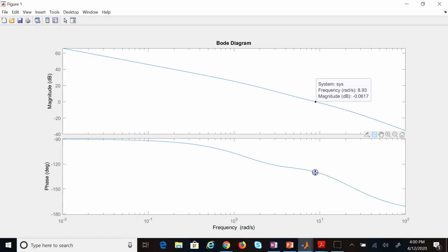It should be about 50 degrees or more. And you see it is. The phase of the system is negative 130, and when you add 180 to it, you get 50 degrees. So although I added 5 degrees extra, my new phase margin is exactly 50 degrees, as I wanted. It's not 55 because the gain crossover frequency shifted.